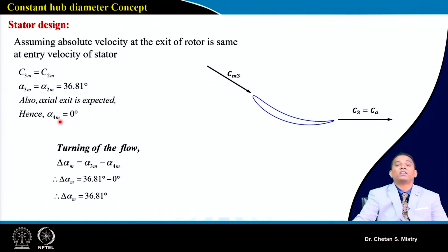There are chances that we will have flow separation or stalling of the blade. That happens for the stator, rather than for the rotor. So it is said to be easy to design the stator, but many times it is very challenging and complex, based on what loading you have selected for the rotor. So we need to be very careful in our calculation, rather than going very aggressively towards a higher number. We need to keep an eye on many parameters.